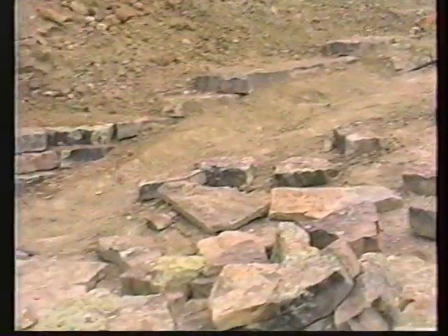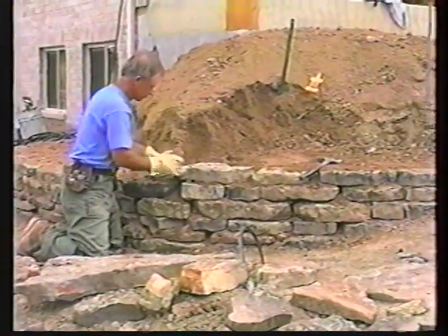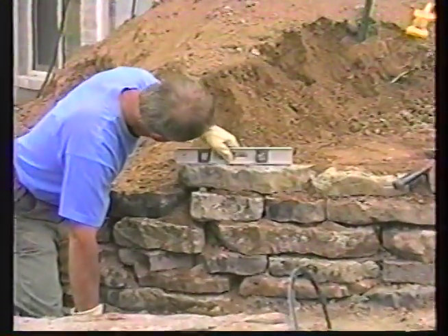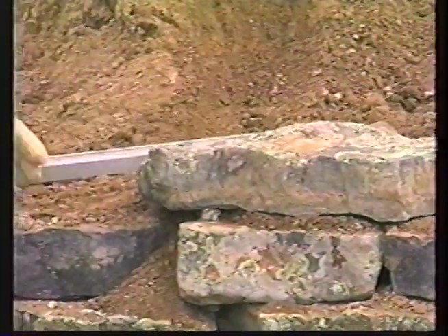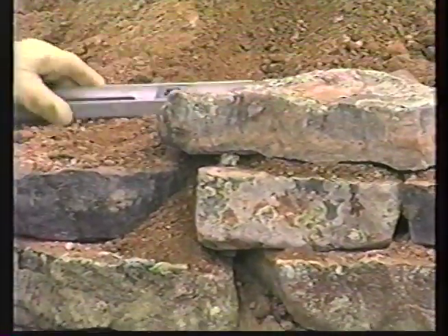To begin the wall, lay out your rocks over a wide area. You're building a jigsaw puzzle with rock, and it's very helpful to have them both close at hand and easy to see. Construct the entire base course first, using the largest rocks for the base course. The base course should also be partially buried in the trench.